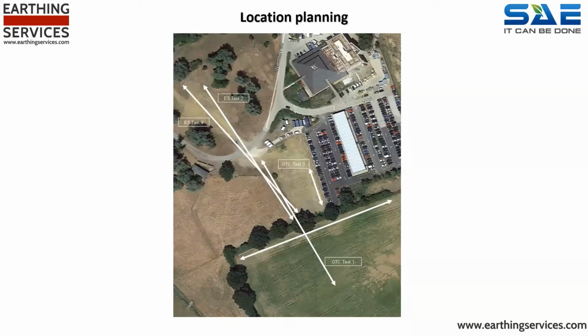From the moment the company receives an order which requires a soil resistivity survey, Earthing Services engineers commence the desktop planning stage of the project. Our trained team knows how to assess the practicality and usefulness of a given area when it comes to undertaking soil resistivity surveys. And this can begin by using topographical data, location coordinates, and plotting technologies. In many instances, simply loading up Google Earth will give an idea as to viability of test routes. Although do remember that Google Earth is not live, and as such, do check that the areas selected remain valid.